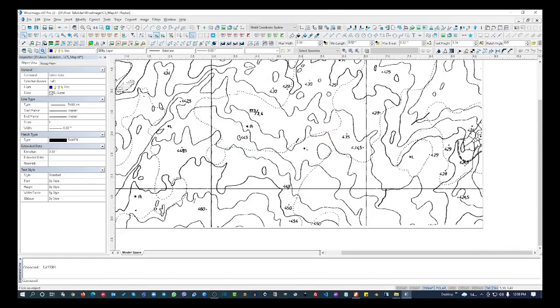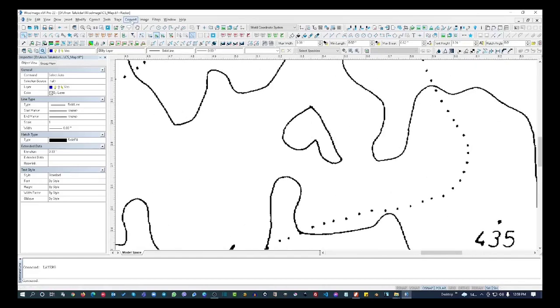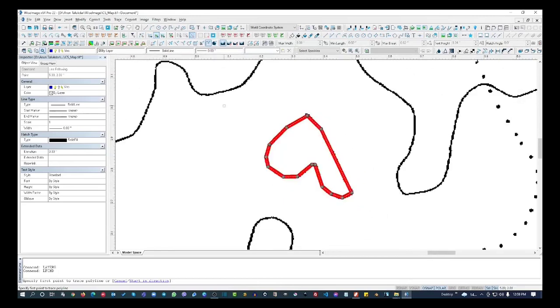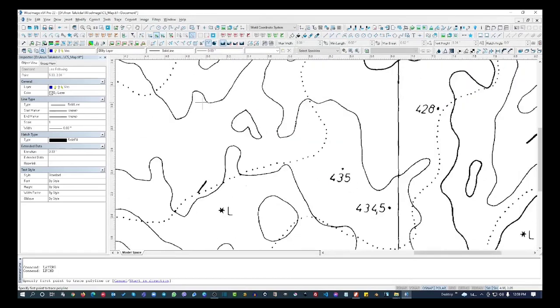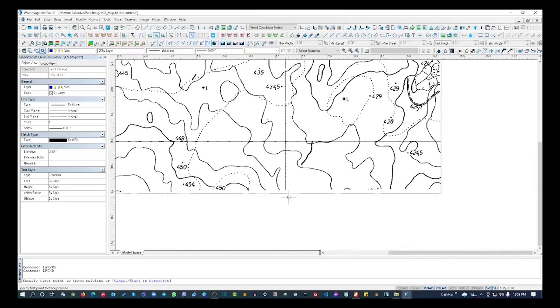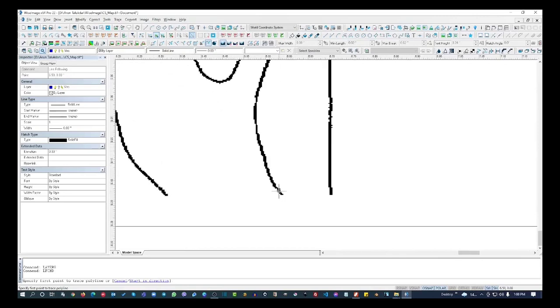And now, this contour, as you can see, we can use these functions for tracing, like we can say line follow, and we can click on this contour, and you see the entire contour was drawn, right? Now, if we take one big example, maybe this one, this is a big contour, so I'll select the contour like this.